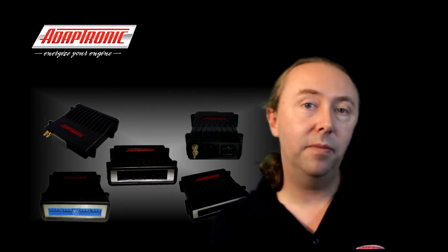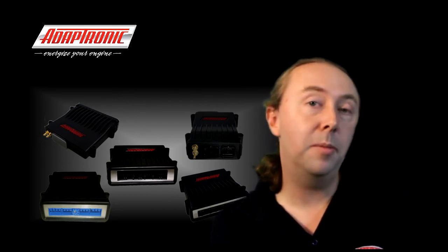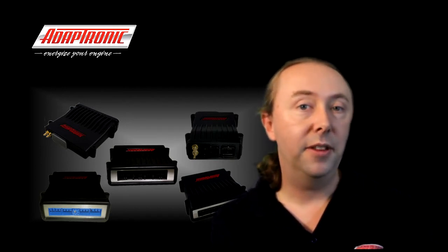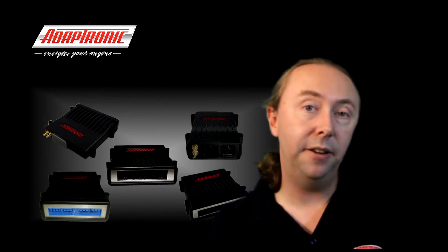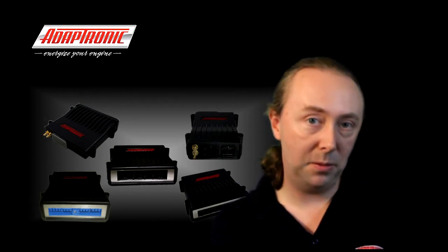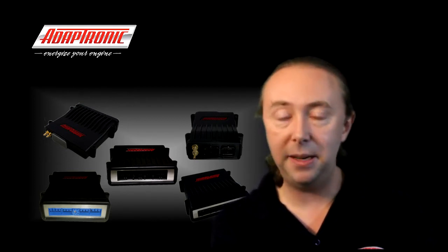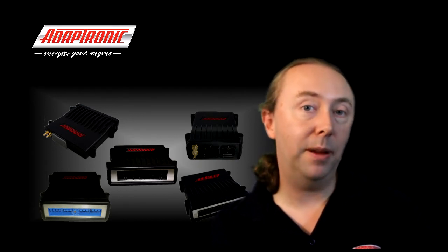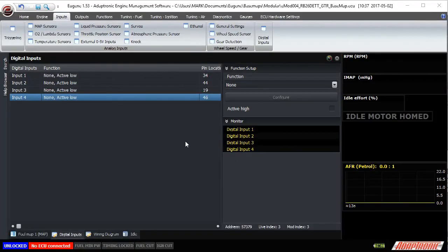Now there are some electrical loads that the ECU will only know about because of external inputs that come into the ECU. So often there'll be a headlight input going into the ECU and a power steering switch input going into the ECU, maybe a blower fan input, that sort of thing. Now generally these are switches which pull to ground when they're being activated. For example, a power steering pressure switch.